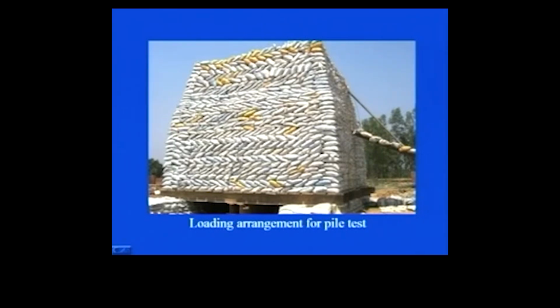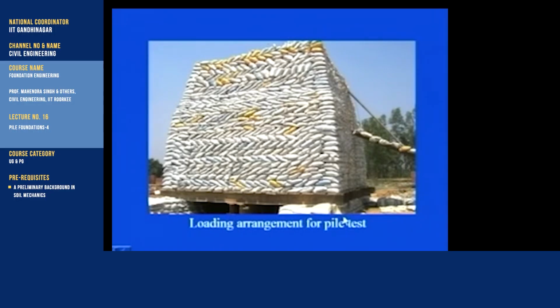So even if one particular bag slips on another one, and there is a little bit of relative movement of these two bags, then how catastrophic it can be, because all the test arrangements are done in a test pit approximately 2 meters deep. There the pile cap, the loading arrangement and the dial gauges are placed. I will show you in the subsequent slides.